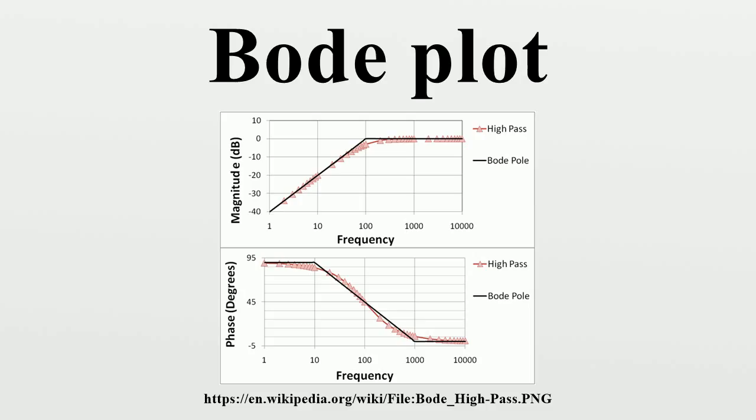After plotting one line for each pole or zero, add the lines together to obtain the final phase plot. That is, the final phase plot is the superposition of each earlier phase plot. Example. To create a straight-line plot for the low-pass filter introduced above, one considers the transfer function in terms of the angular frequency. The above equation is the normalized form of the transfer function. The Bode plot is shown in Figure 1 above, and construction of the straight-line approximation is discussed next.